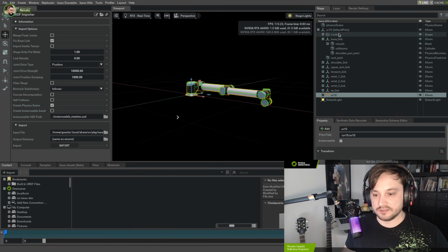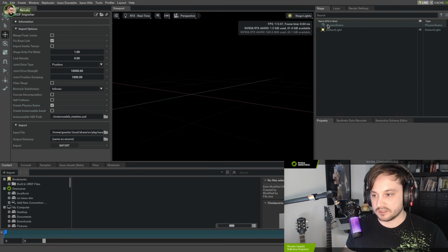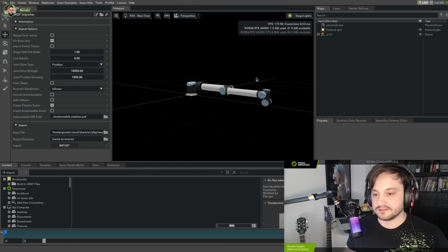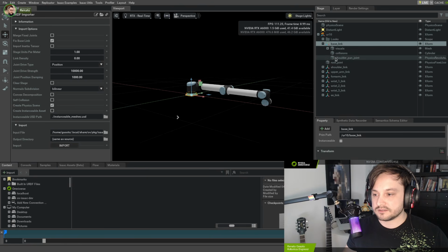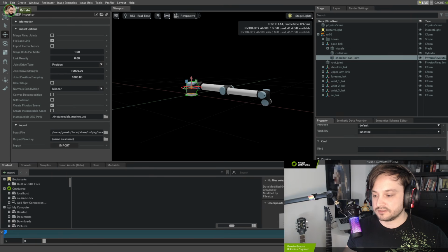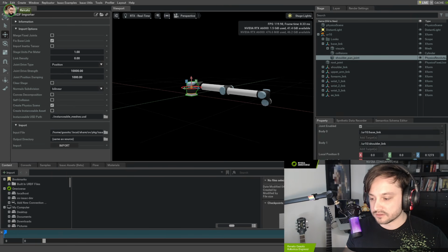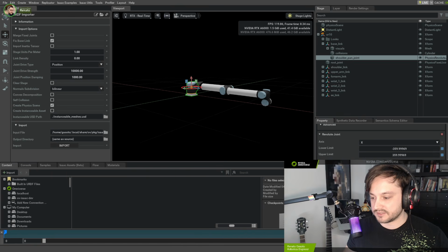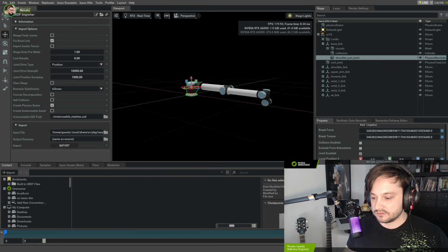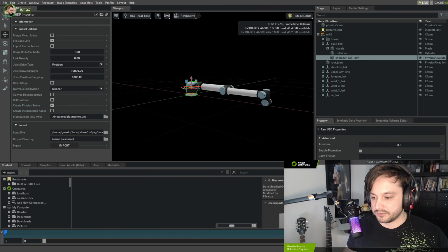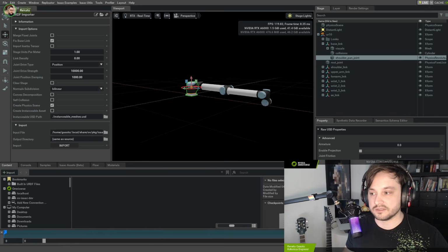And here's the new UR10 that we just got. Let's do it again. No worries. Here we go. Base link, shoulder joint, and this should be for all joints, but let's go on this one. Yeah, max force 330, and also on our raw parameters, the maximum joint velocity. So the URDF importer, as it is, does import the efforts from the joints as well.